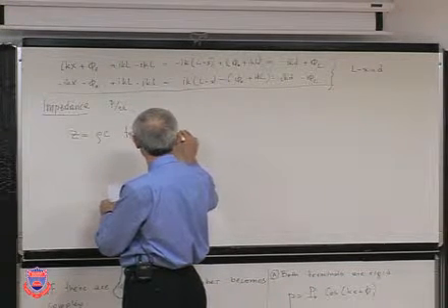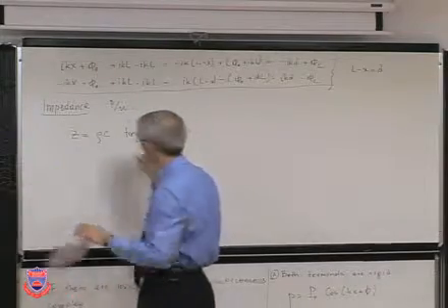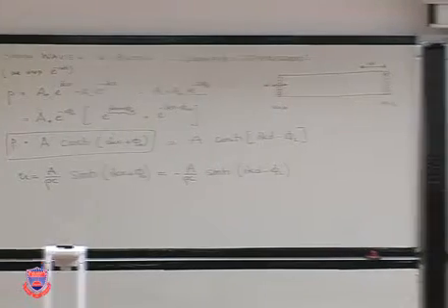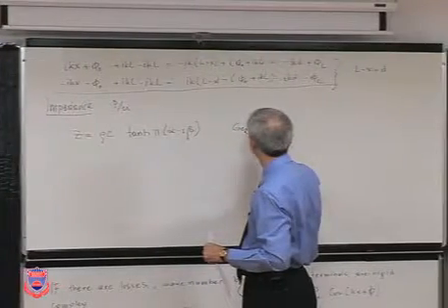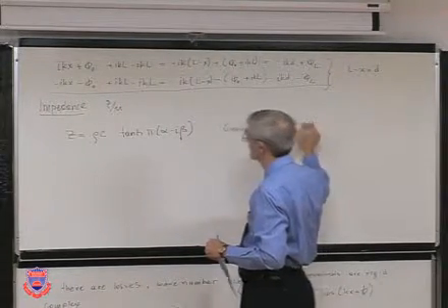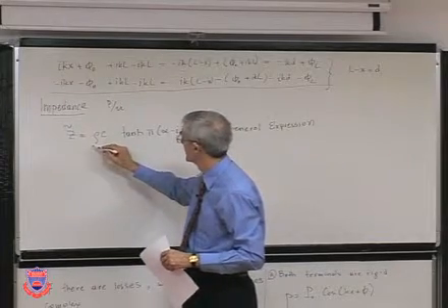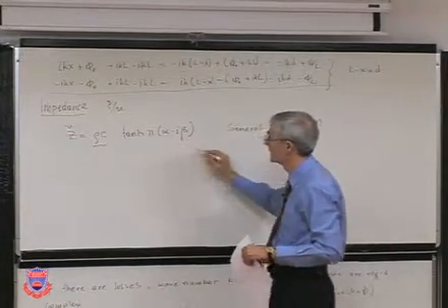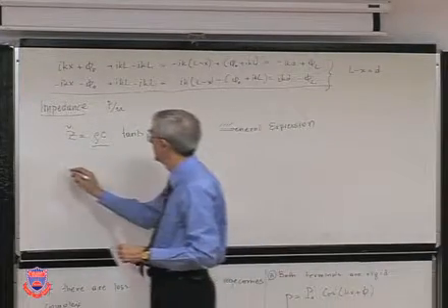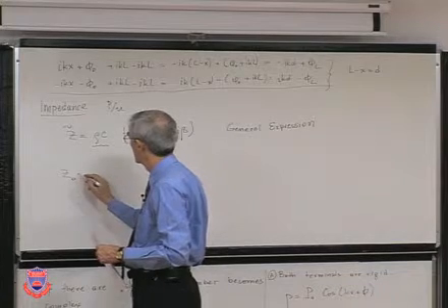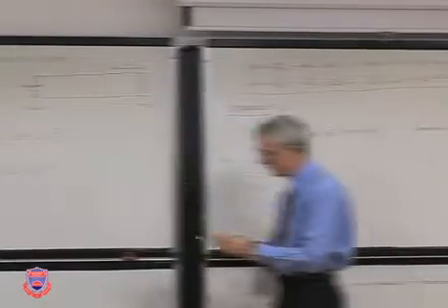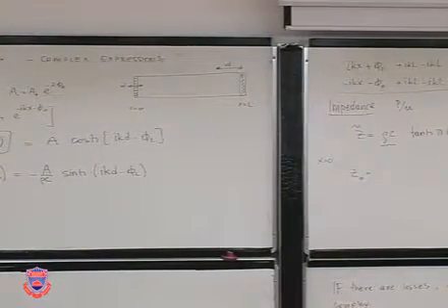Actually, this is not the division of these, but we're expressing a general expression in complex terms, where the specific acoustic impedance is some complex relationship between the two. And what I want to do now is, at x equals 0, equate this to this value.